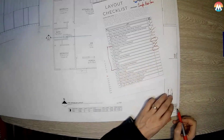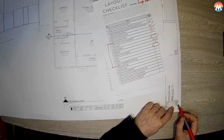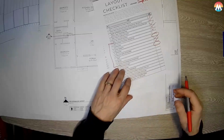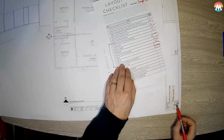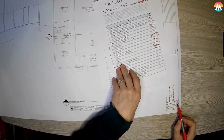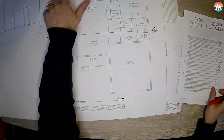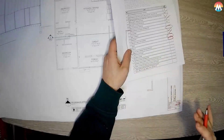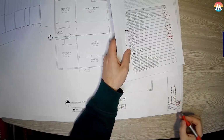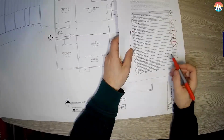Next thing is date. And you know what? It looks like this is from the last time we did the iteration of this course, so the date is about 6 months old, so that really should be updated. So the scale here, now under scale it says noted here. And that's what it should say, because that's just referring that each of these views have their own. These ones say not to scale. So not everything on this page is the same scale. So we can't say that it's all one scale. We're just saying that they're noted. There's different scales that are used, so that's correct.